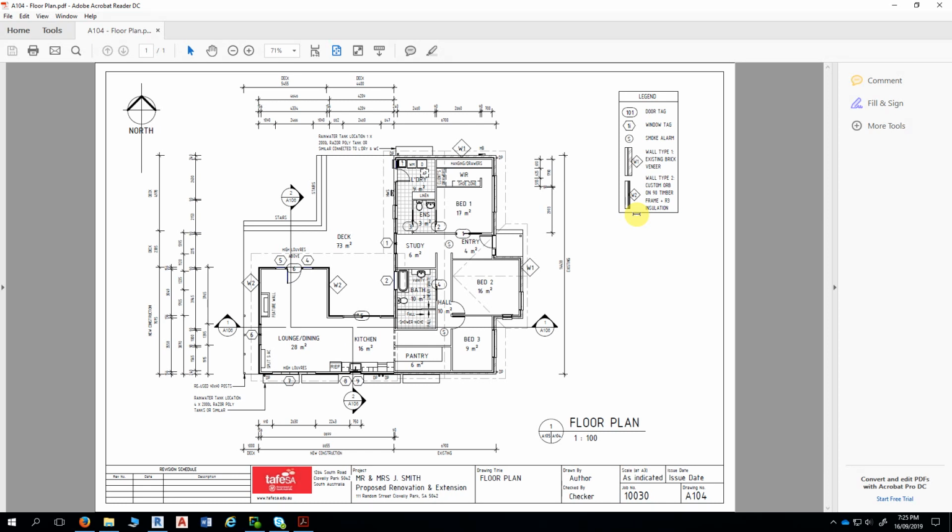So after we finish the floor plan itself, we'll actually move on to the demolition plan. So that's our next view that we're going to work on. But for now, if you can just put your north symbol in approximately here in relation to the floor plan itself, and then we'll have a look at adjusting the crop region, and the floor plan is then ready for its sheet.